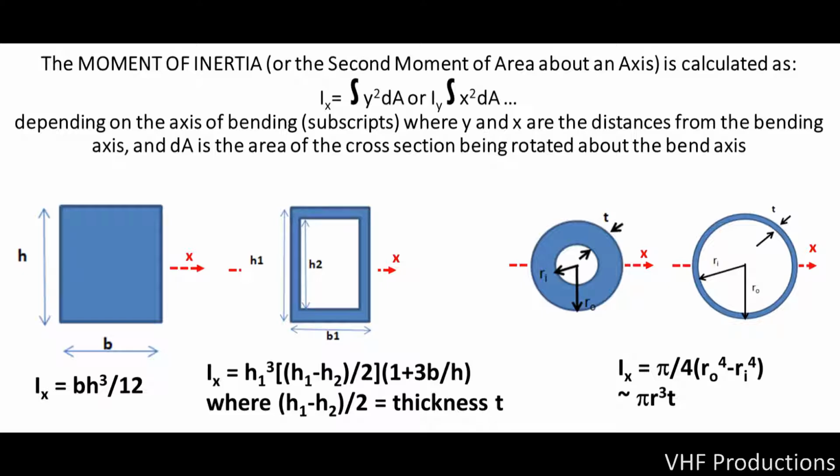One is a thick-walled cylinder, and the other is a very thin-walled cylinder. But the mass per unit length in each of these was chosen to be very similar to each other. Sufficiently similar masses for the pairs of bars, that differences in the stiffnesses will be attributable to the geometry rather than the overall mass of the bars themselves.